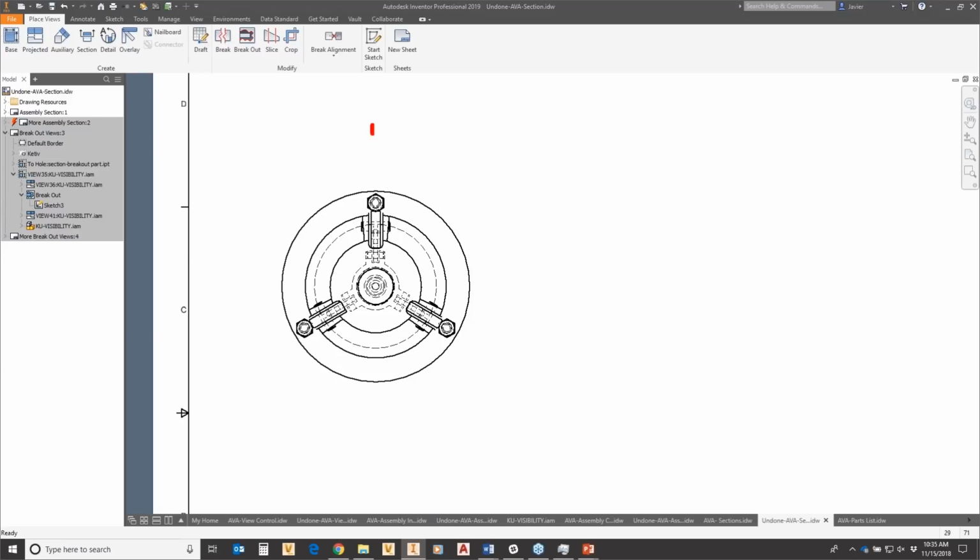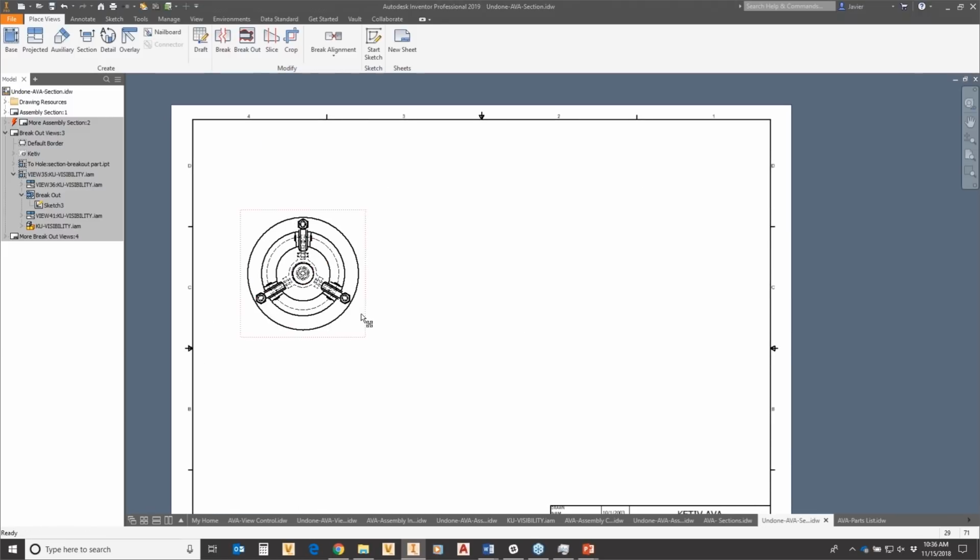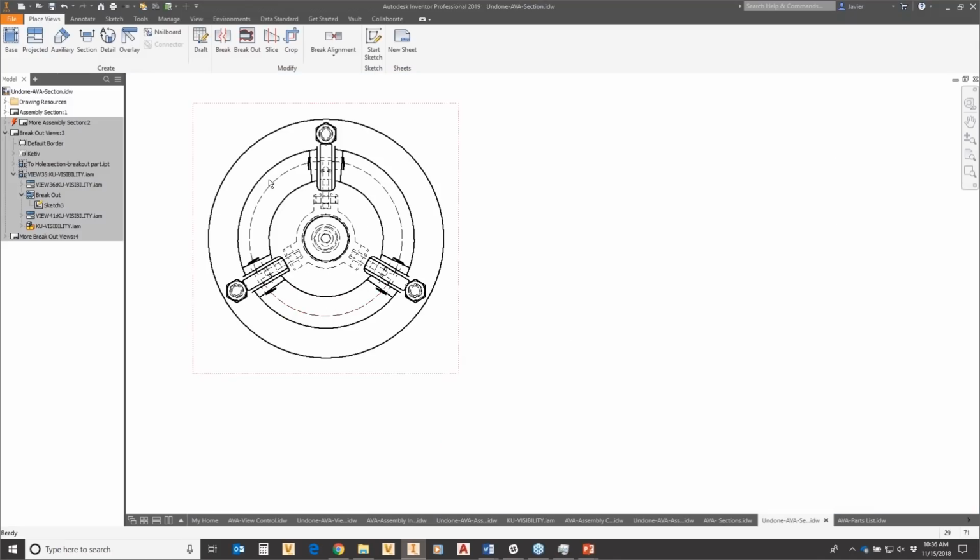As soon as you start to go towards the center and create your section line this way, you can create what's called a rotated section. It's just something to consider when you have parts like this that don't necessarily section evenly. Okay, so let's go ahead and create that section. Here's a section tool, right?